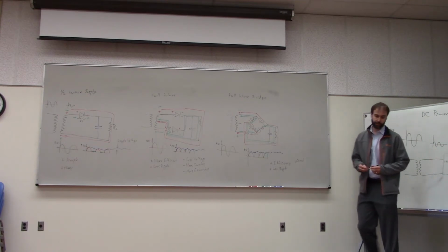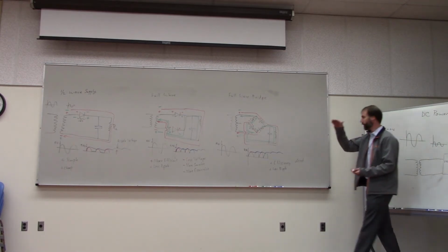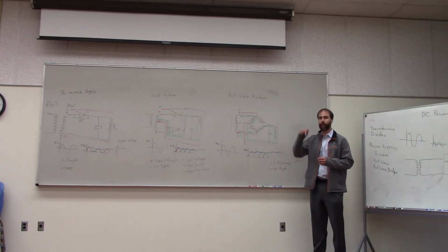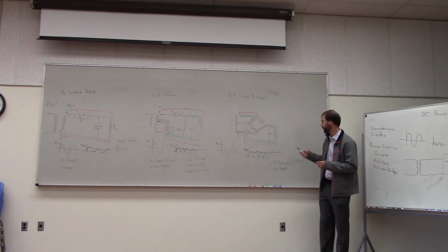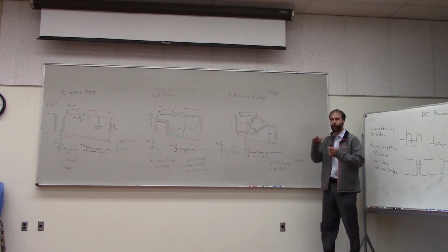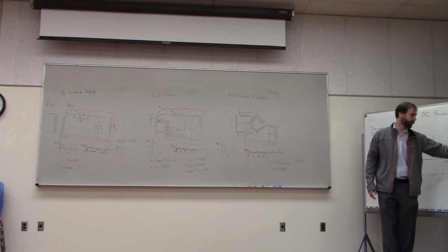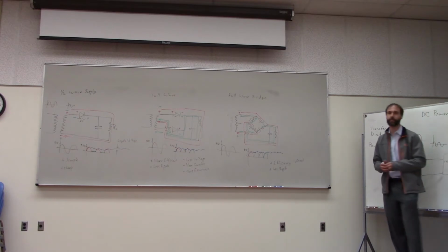So it uses a digital regulator that either turns the signal on or off. And when it turns it on and off like that, it creates a square wave. And it does that really, really fast, so that's a high frequency square wave. And then it does some filtering on that that makes a very nice, smooth DC signal. So that's how that type of regulator works.